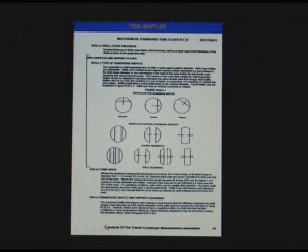This shows the type of baffles that are available in shell and tube exchangers. They'll typically be selected based on the pressure drop and maximizing heat transfer considerations. This is a typical segmental baffle with a horizontal cut. Basically, the fluid flow will go up and down. We'll have a more detailed presentation of that.